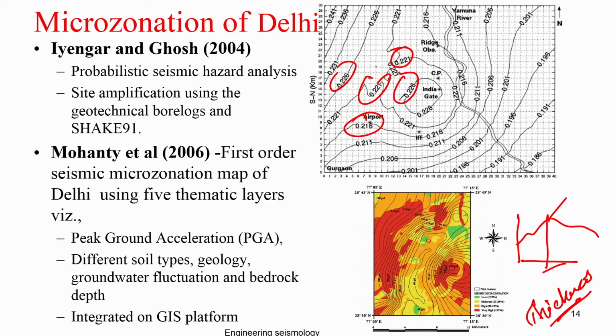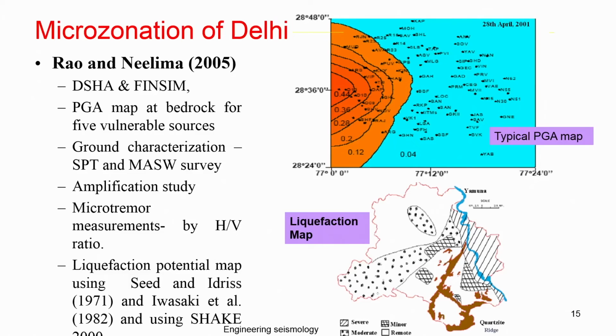It does not give you that kind of map by using microtremor studies alone, because we have used microtremor studies for different cities, and we found that the predominant frequency depends on soil, and you establish a relation between soil thickness and predominant frequency. If there is a change in this, the estimation can be completely wrong. One has to remember that. But there are people who carried out this kind of study and claim that that is the microzonation.